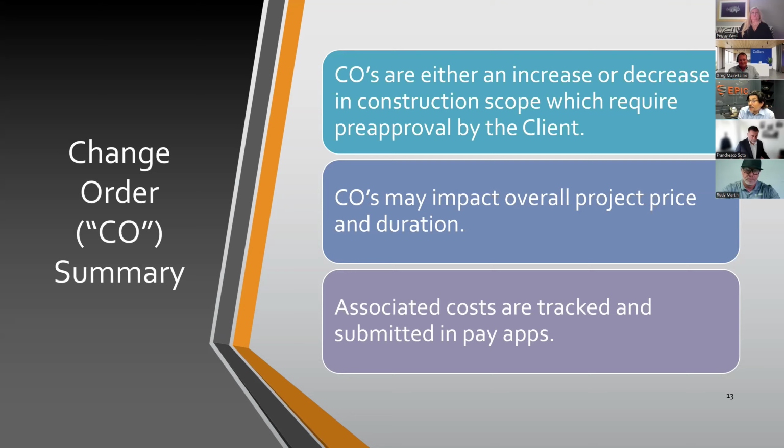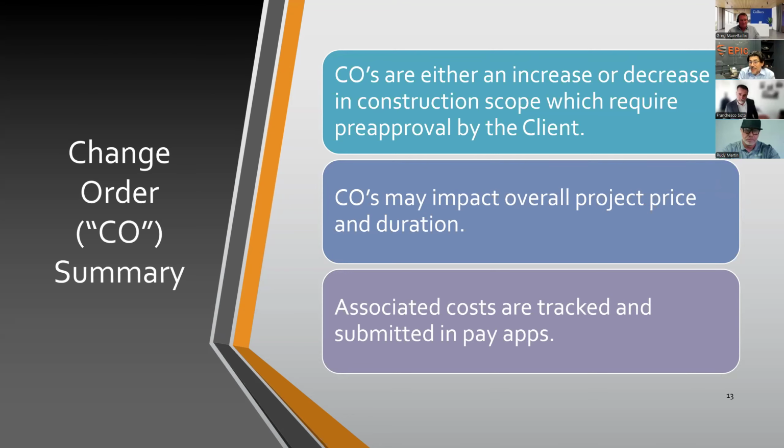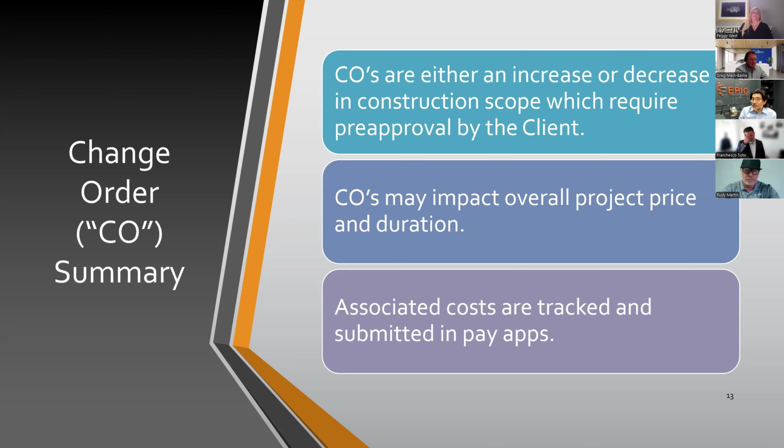It could be a variety of different things. Obviously, change orders have a very negative connotation, but there are some good change orders that we don't want to overlook, like negative change orders towards the end of a project if certain monies weren't spent on the estimated quantities, or change orders that track weather delays, for example, which is, I guess, a middle ground as far as being good or bad.